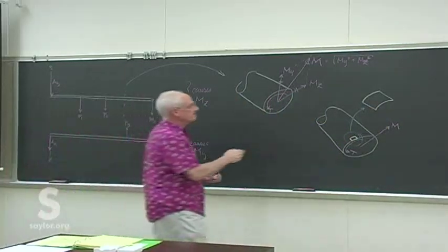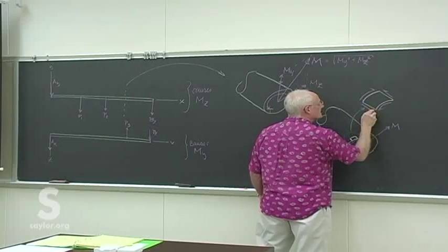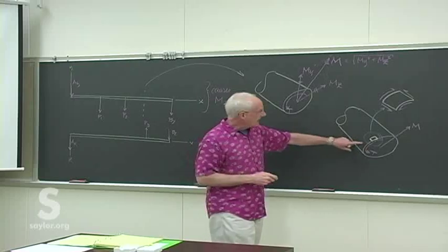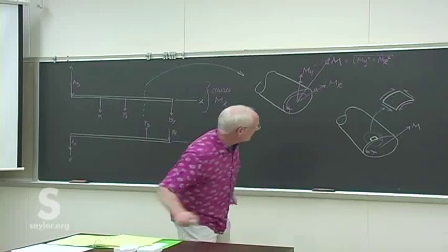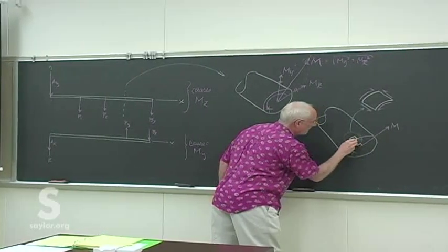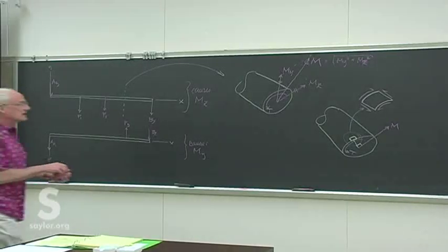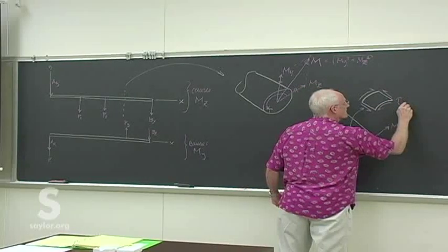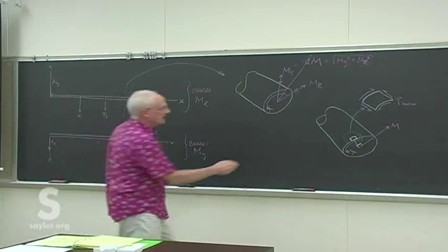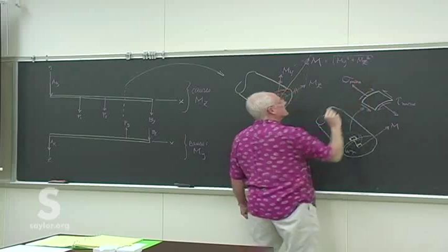And we know because of the torsion, we'll see shear like that because of the torsion in the direction I happen to pick. And in fact, we know that if we're taking the particular element direction so that the plane of this element is parallel to our net moment, then these are all maximum values. And so we'll have the maximum expected shear stress. And for the picture shown, because of this bending moment, we'd have maximum expected shear stress on that face.